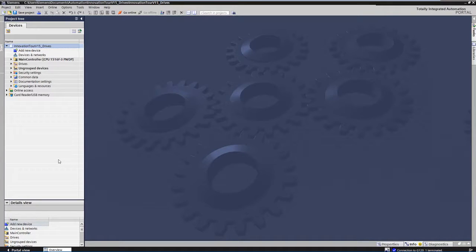This configuration test, which is specified in the drive standard DIN EN 61800-5-2, is intended to detect potential project planning errors and document the correct function, like whether the parameter setting matches the machine. To do this, an intuitive tool is offered in Startdrive that guides you step by step through the acceptance of the safety functions. At the end, you will receive finished standard compliant documentation which can be attached to the machine documentation. This means easy handling and that you save a lot of time.